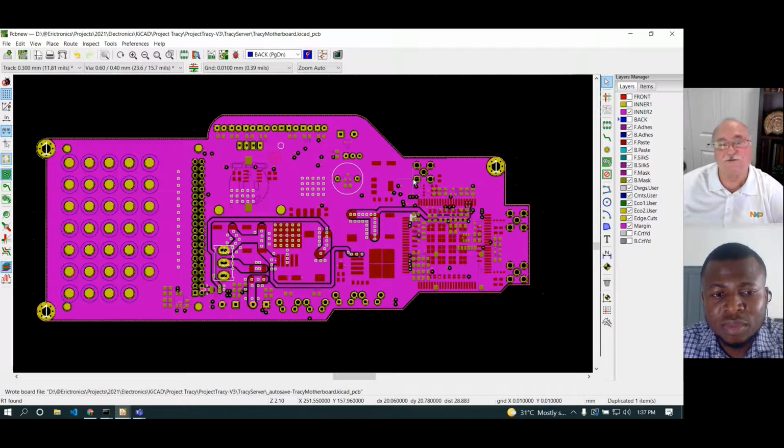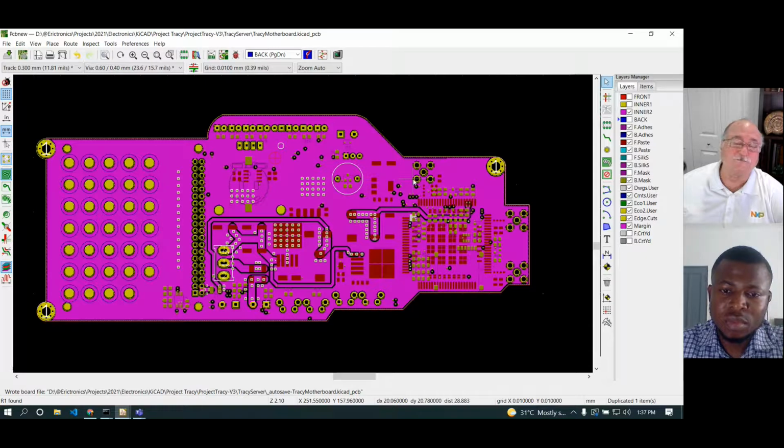And it basically makes that transition from one dielectric to the next invisible to the path of the signal. And it provides a lower impedance path. So the energy much prefers to do that movement between the layers as it finds places to be consumed. So this is a very powerful tool or process to use, especially if you can from power supplies.